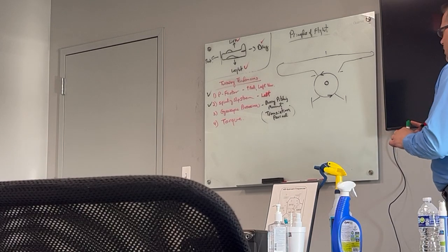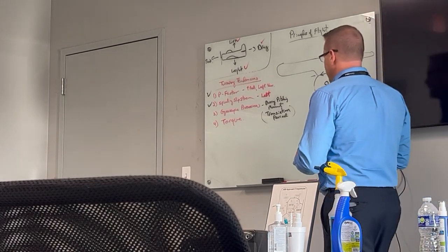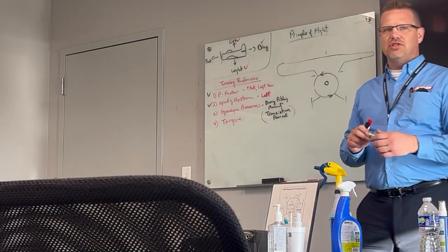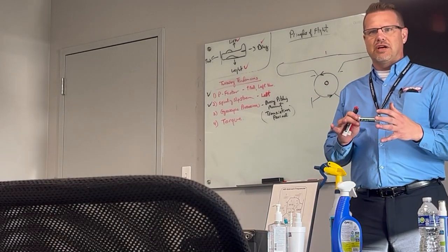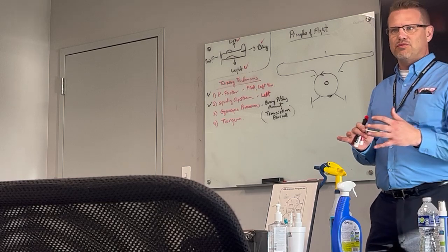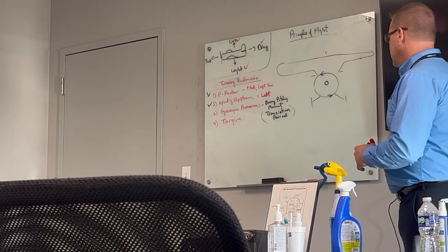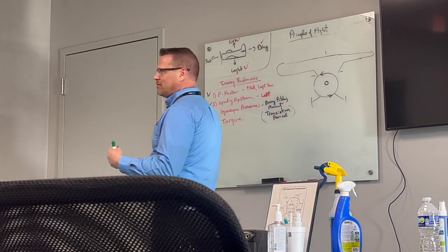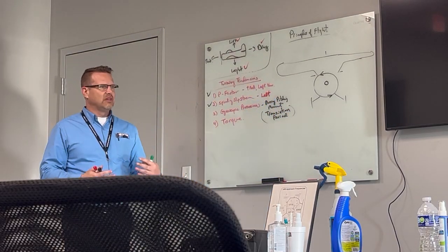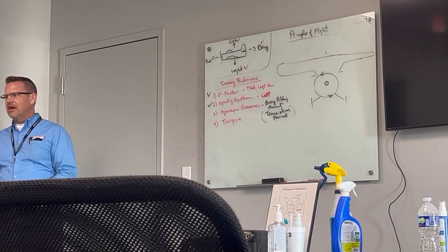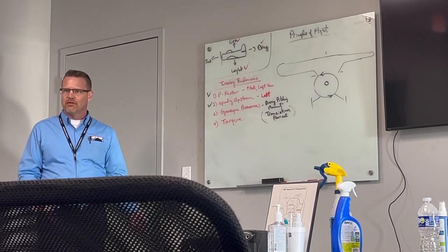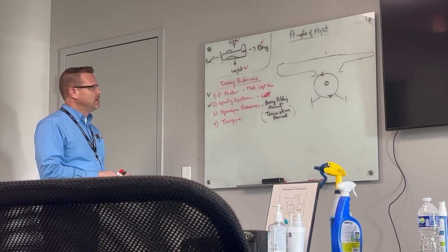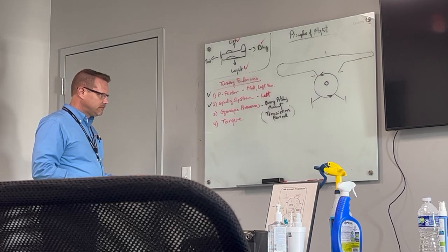So we have two different types of gear. We have conventional gear and we have tricycle gear, right? So it's typically explained, these gyroscopic effects on takeoff is when we kind of feel them the most, okay? Again, because we're going from 0 power to full power, we have relatively less authority on our flight controls because the airflow's low, so we don't have good authority. We get a lot of feeling of this gyroscopic precession on takeoff, or effect from it.